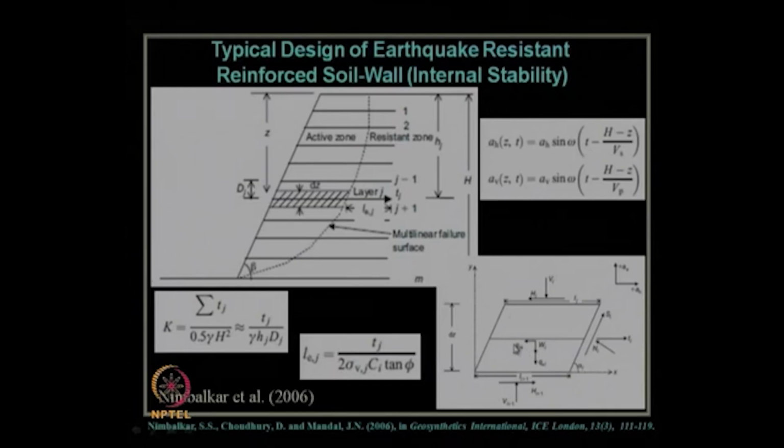Here we have used pseudodynamic approach, because as I said, Dr. Nimbalkar developed the pseudodynamic approach and he used that method for all his analysis. So, these are the input seismic accelerations in horizontal and vertical directions, the sinusoidal seismic acceleration. Finally, the results are obtained in terms of this parameter k.